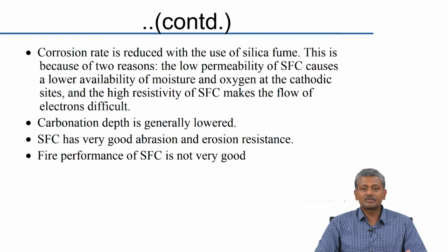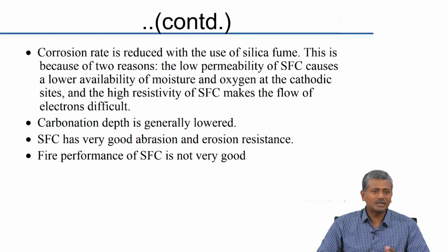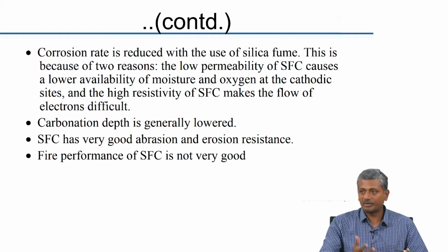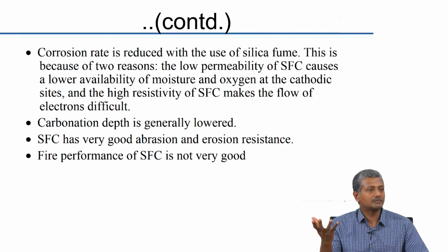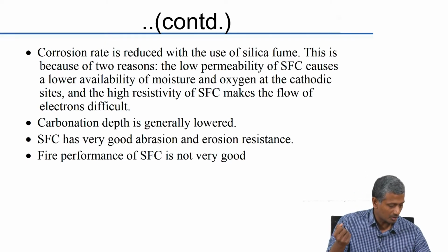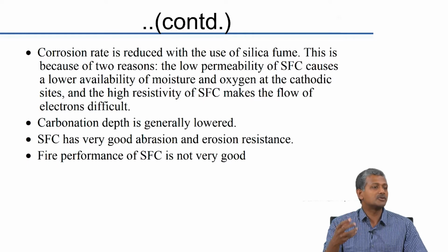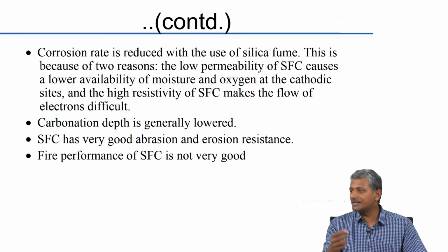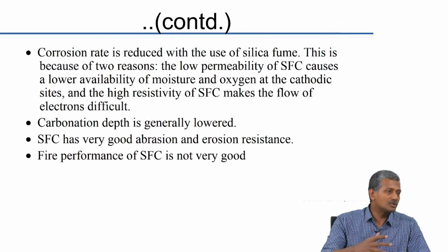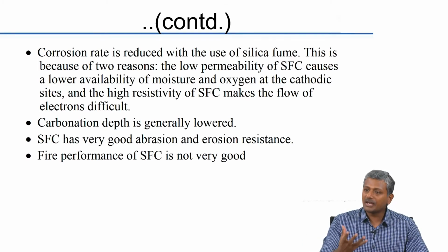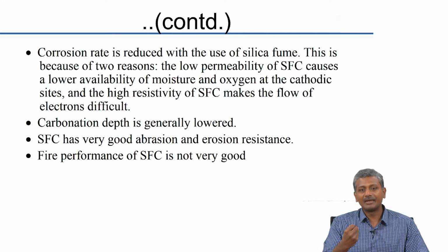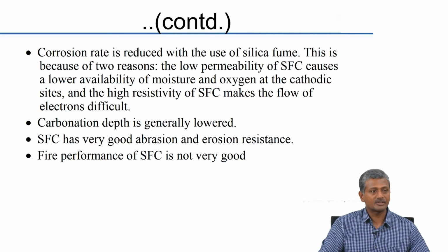Fire performance of silica fume concrete is not very good. And why do you think that may be the case? Yeah, when fire happens, heat is generated in the concrete. When heat is generated, there is moisture in the concrete that has to come out, and this moisture wants to come out almost immediately by transforming to steam, right. In normal concrete, there is enough connectivity, the ITZ, for the steam to come out without any difficulty. With silica fume concrete, the steam can actually build up within the system and cause explosive failures happening to the concrete.